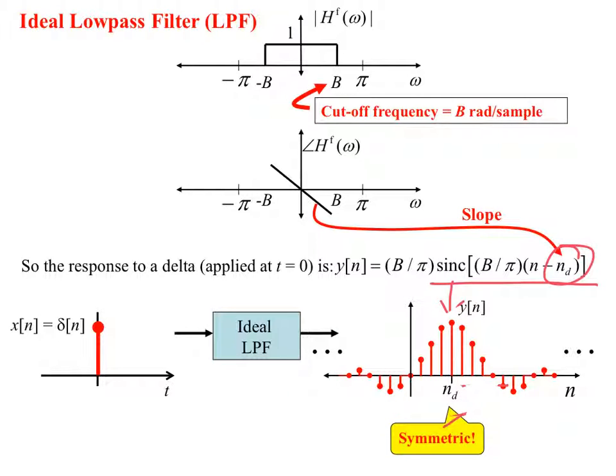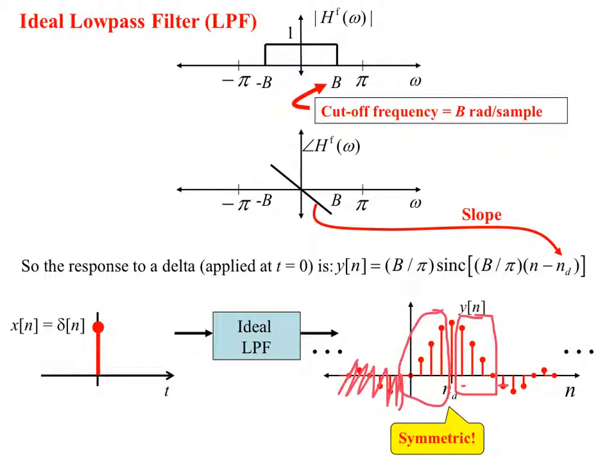But basically what we're going to do is turn this into a causal filter by truncating. First we'll throw those away, and then we need to make this symmetric to have the linear phase. So if we're keeping only these things to the left of that center point, then we should keep the same kind of structure to the right.